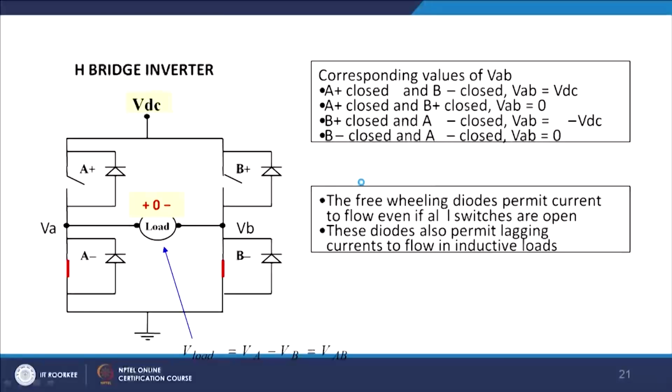So, how can we realize this SPST switch? We have seen it for the DC converter. Let us see how we can do the same thing for the inverter application. So, this is the application. This is a load and the voltage is 0. This is basically A and B. A blocks, B blocks and C closes. So, the voltage across it will be basically 0. So, our lower two switches have been closed, so you are getting a 0 voltage.